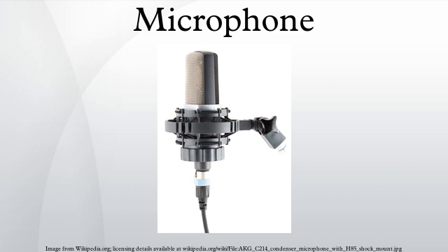This is a practical concern but is not directly an indication of the microphone's quality, and in fact the term sensitivity is something of a misnomer, transduction gain being perhaps more meaningful, because true sensitivity is generally set by the noise floor, and too much sensitivity in terms of output level compromises the clipping level.